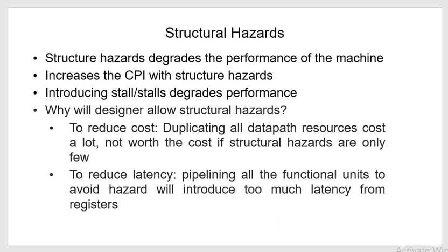If these are the disadvantages of the pipeline structure having the structural hazard, then why would a designer allow the structural hazard? So we will mention here 2 reasons. One is to reduce the cost and to reduce the latency of the unit. To make the unpipelined structure into the pipeline structure, all the functional units will have to be duplicated, and it may be too costly.